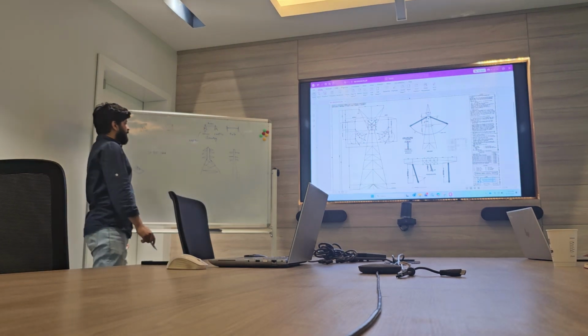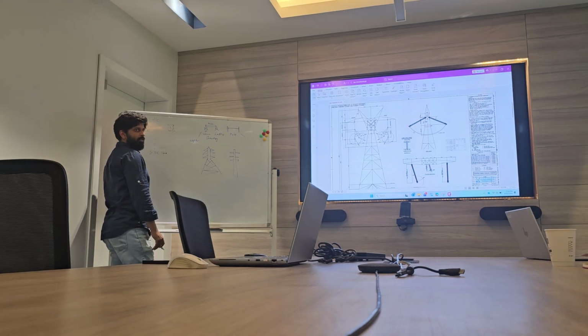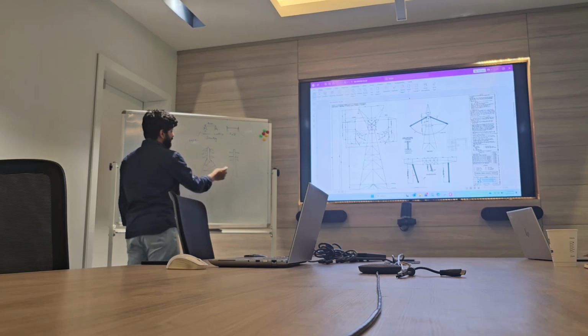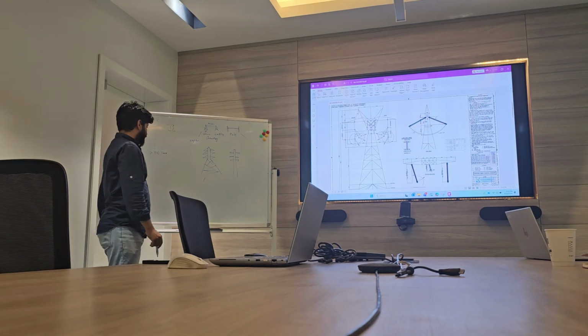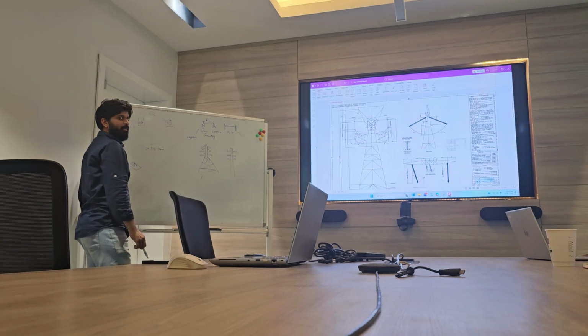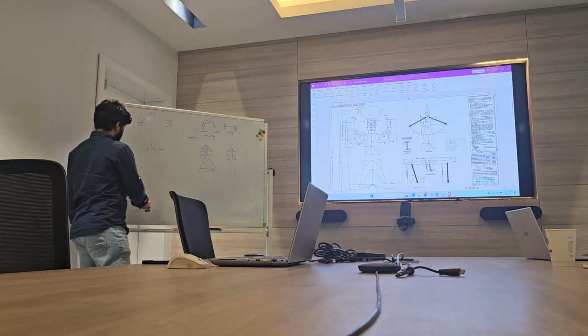The pole is mainly used where you have open area, large space. This is cheaper. Why do we need lattice when this is cheaper? Flexible. What is the right of way? You are not allowed to build in just any area. We have restrictions; many lands belong to someone.